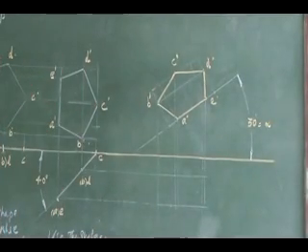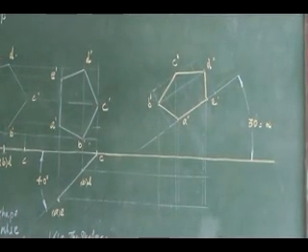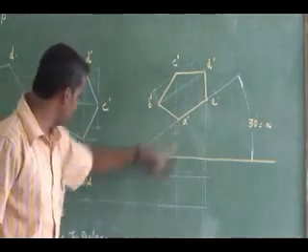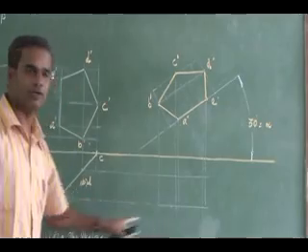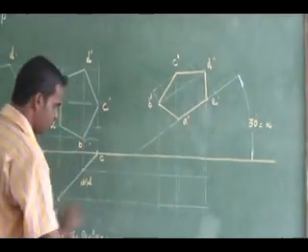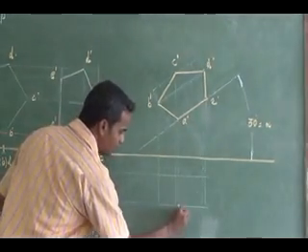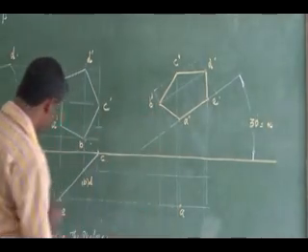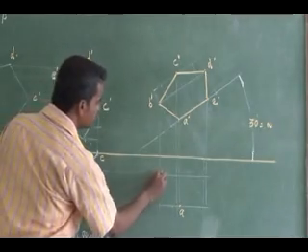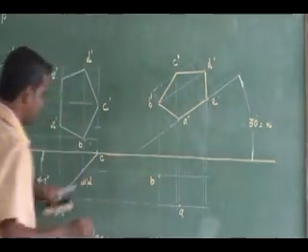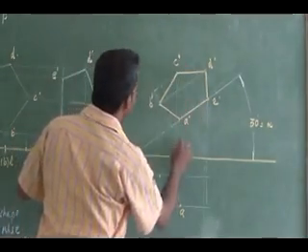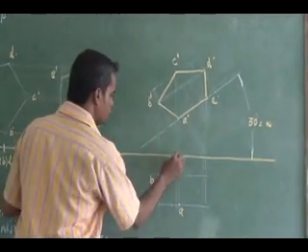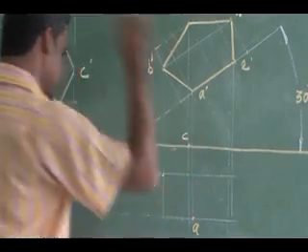Now, carefully you have to get your final top view. How can I obtain the final top view? At the top view location, wherever A and A are meeting, mark that A. Where I have B and B, this is going to be my B. C and C: C is on the reference line, so C is here.